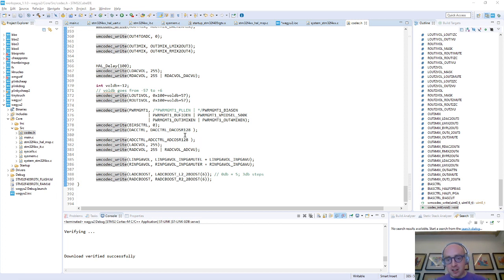Right, that was the I2C. Yeah, your bitbang I2C is probably less overall code than using a HAL I2C library. I agree. I really don't like the I2C libraries, and their API sucks. It doesn't let you do stuff like skip a stop condition. You feed it stuff, and it always does a stop condition, and it does it through a nasty tangle of IRQs and stuff. It's just gross.